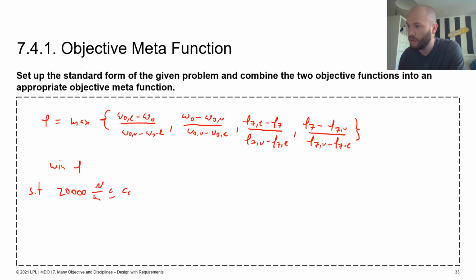So with the upper and lower bounds for the chassis springs, and also we have the upper and lower bounds for the anti-roll bar, and the upper bound is 50,000 Newton per meter. And if you solve that, then you end up with the following values.